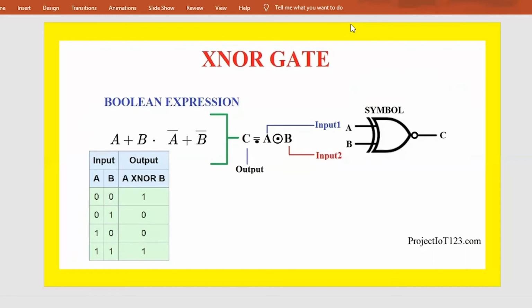In fact, both NAND and NOR gates are so-called universal gates, and any logical function can be constructed from either NAND logic or NOR logic alone. If the 4 NOR gates are replaced by NAND gates, this results in an XOR gate, which can be converted to an XNOR gate by inverting the output or one of the inputs.